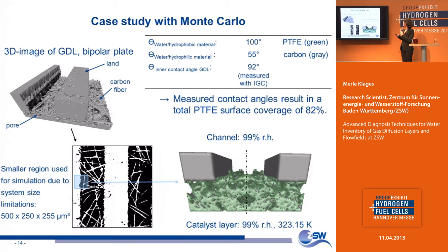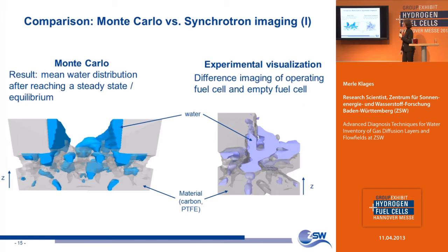And afterwards, within the fuel cell, well, for the given operation conditions and the given hydrophobicity of the GDL, we simulated where the water could accumulate. Corresponding to the surface energy of the hydrophobic and the hydrophilic material, the program decides where it's most probably accumulating the water.